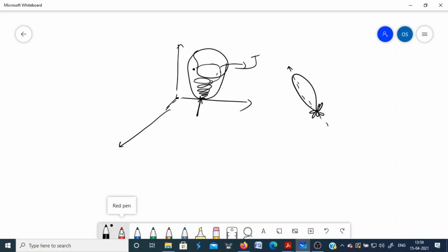This is the direction of the main lobe of the radiation pattern of a linear array of antennas. If you want to change it to this direction, that can be done using adaptive filters, which is called adaptive beamforming. This is what is called spatial filtering, where we also use adaptive filters or Wiener filters.